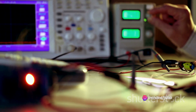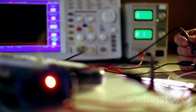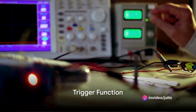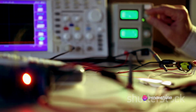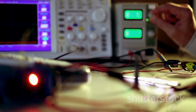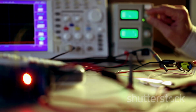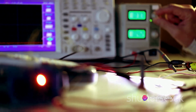The oscilloscope also has a time-based circuit, which ensures that the horizontal sweep happens at a constant and adjustable speed. This allows you to measure the time period and frequency of the signals. Now, on to the trigger function. It gives you control over when to start the horizontal sweep. By setting a trigger level, you can start the sweep when the signal crosses a certain voltage. This helps in stabilizing repeating signals and capturing non-repeating ones.